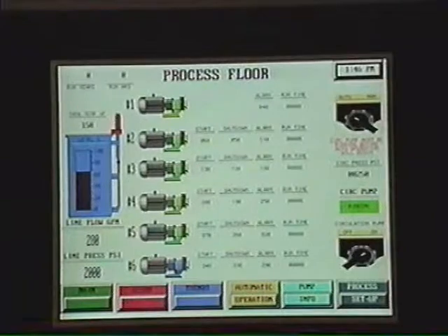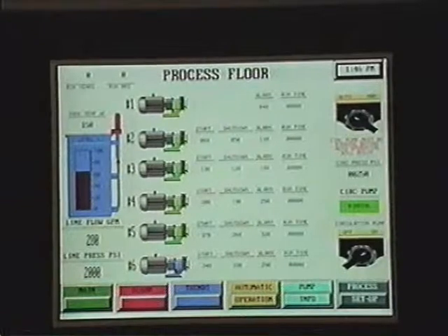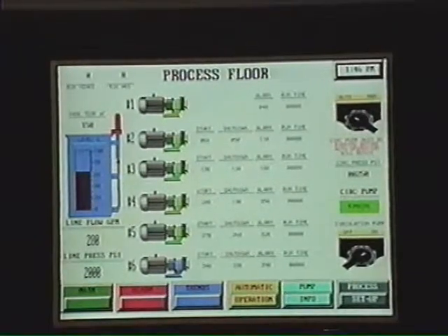What that means is if the flow drops below 390 GPM and your pressure drops below a predetermined set point, then in 30 seconds this pump will go into alarm and give you an alarm condition. The pump will continue to run, but it will show alarm and the next pump in line will start, unless of course it's pump number 6, which has no other pumps in line.